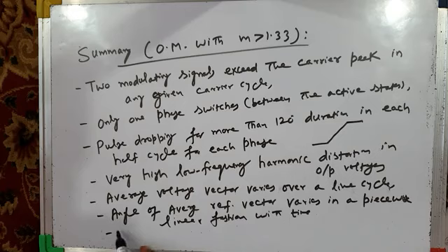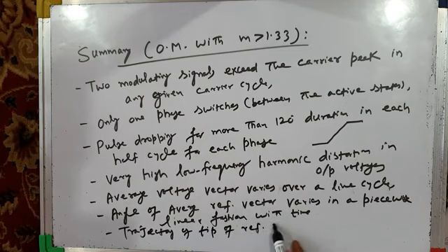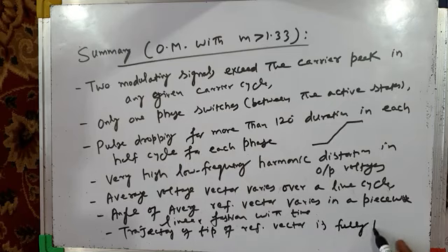And finally, what about trajectory? Trajectory of tip of rotating reference vector. Tip of reference vector is fully hexagonal, not circular at all.